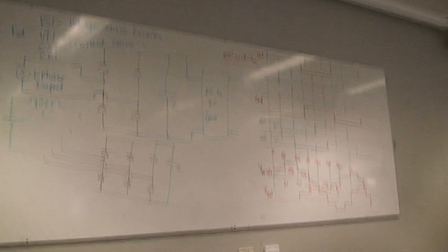The whole idea is that the inductor will not allow the current to change quickly, so it can act as a current source. Usually you can make a current source by using a transistorized circuit, a voltage follower kind of circuit where the current is constant, but for large current you can make it like that. So you can have either voltage source or current source, but most commonly used is the voltage source inverter, because the supply is the voltage for most cases.